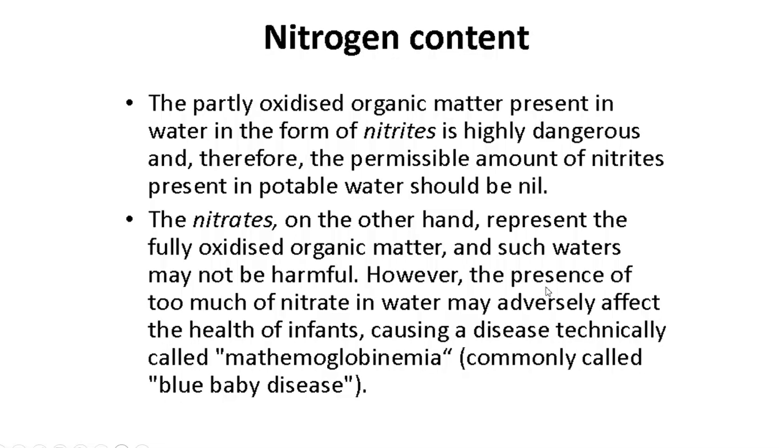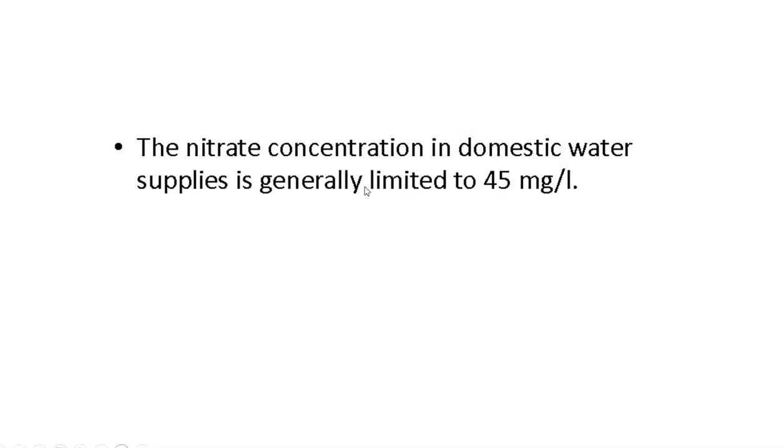However, the presence of too much nitrate in water may adversely affect the health of infants, causing a disease technically called methemoglobinemia, commonly called blue baby disease. The nitrate concentration in domestic water supply is generally limited to 45 milligram per liter.